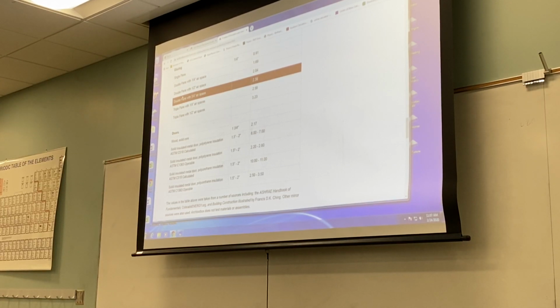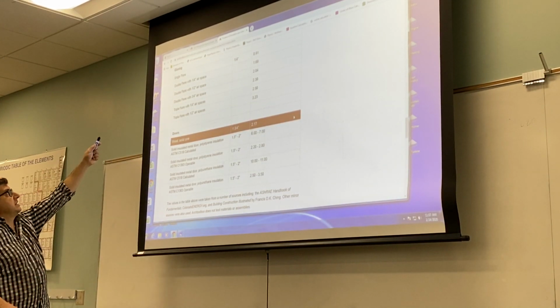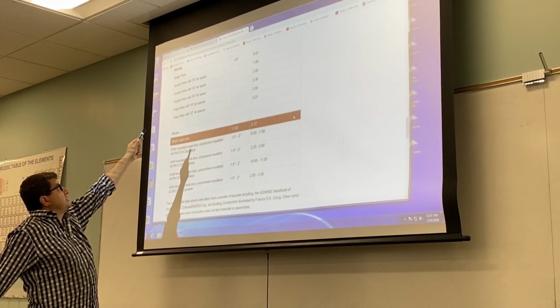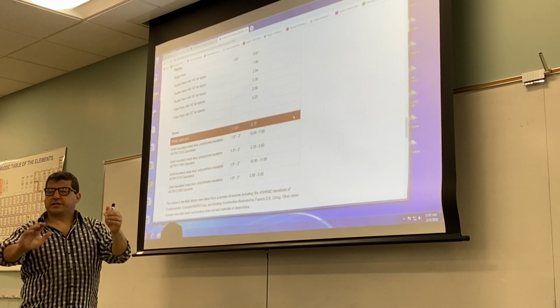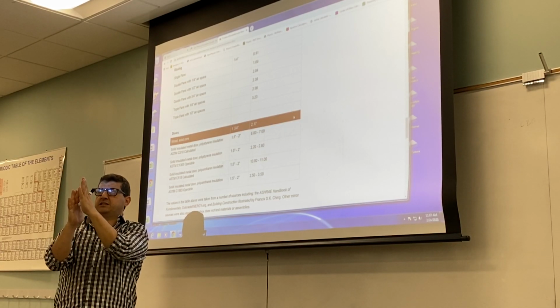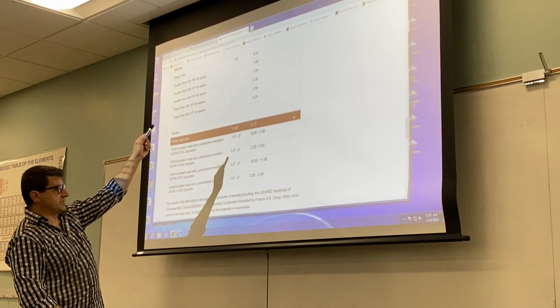Glazing: double pane, single pane. You see, oh yeah, that's very important, the windows, right? Single pane is 0.91. Double pane with a 1/4 inch airspace. So double pane windows are basically two layers, and inside is an air layer, right? So 1.69.